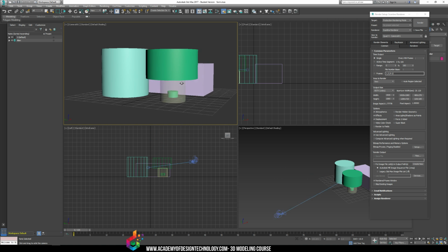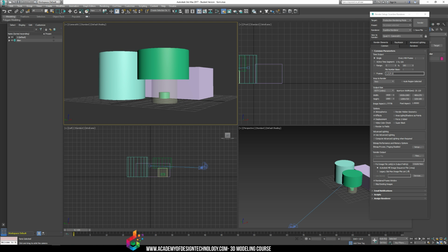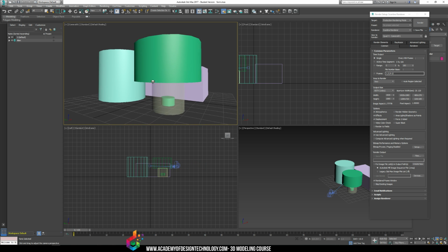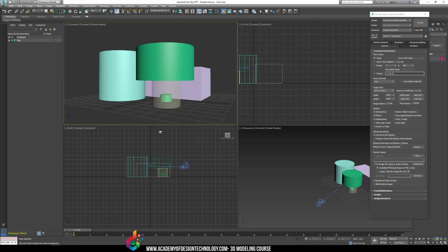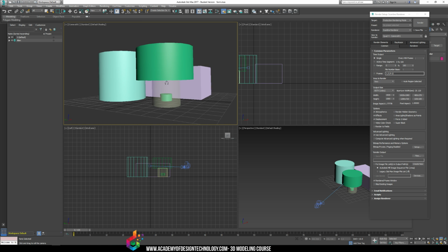For instance, if I go here and I'm looking at your scene, this is kind of how your scene might look. You just have the alien ship and kind of the silo and the farm. But if I play around with the perspective, left click here and it's on perspective mode, we get this nice, weirdly alien-looking scene where the UFO is a little too close, the silo and the barn are a little in the background there. It makes a really interesting thing. So don't forget to play around with things like perspective, maybe add a slight camera roll, make it a little unsettling at an angle.